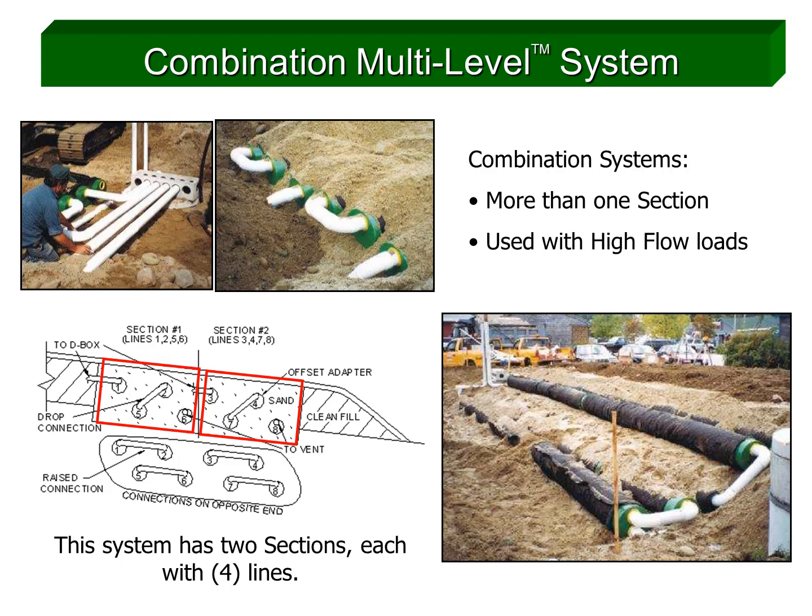Combination systems, whether single or multi-level, are referred to as high-flow systems because the daily loading exceeds 900 gallons per day. Taking a closer look at this illustration, you can see two serial sections outlined in red. That would mean this field has been designed for a daily flow over 900 gallons per day, but not more than 1,000 because each serial section can only accept 500 gallons.